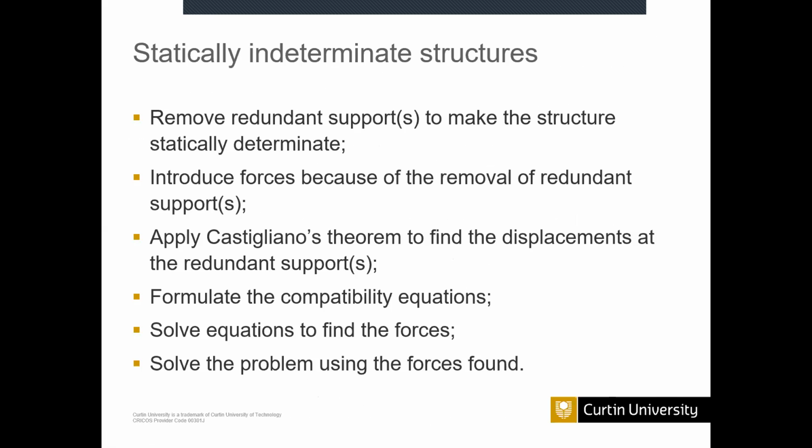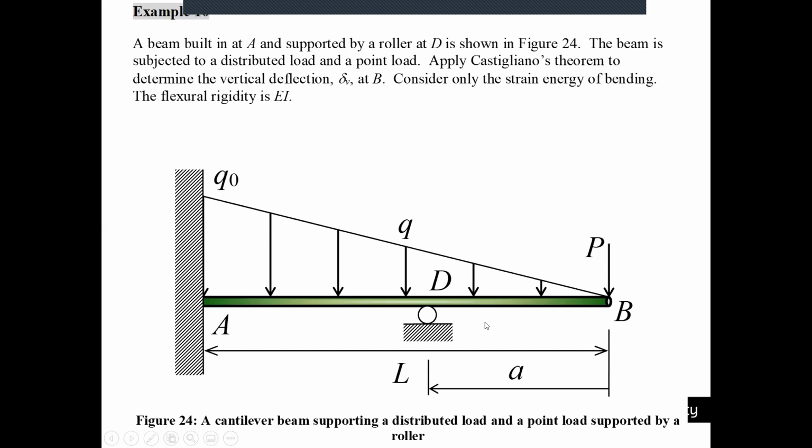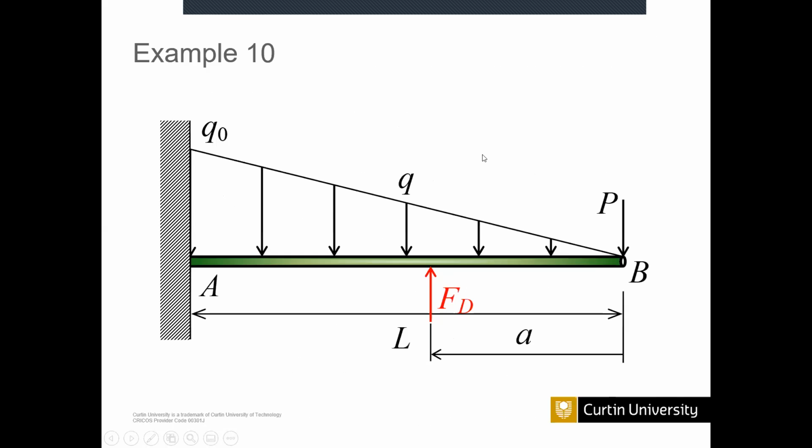So in here, you need to find that force using this Castigliano theorem. Statically determinate means that if they give the FD value, FD equals this value, then you don't worry. In here they didn't provide the FD value. They only told us there is a reaction, and definitely we should know there is no vertical deflection.